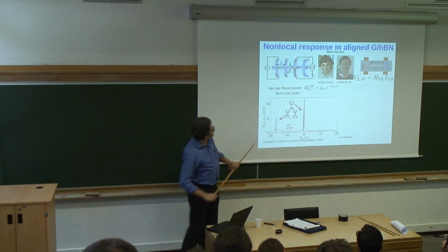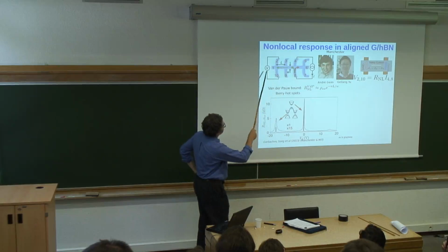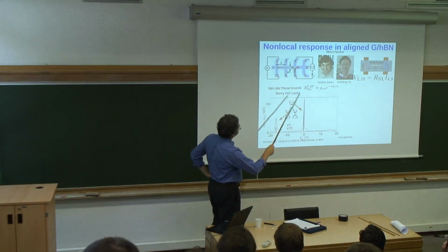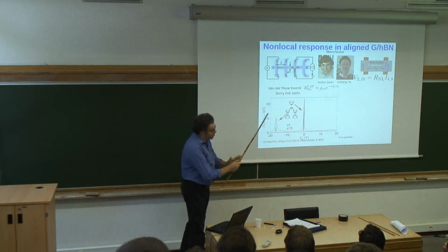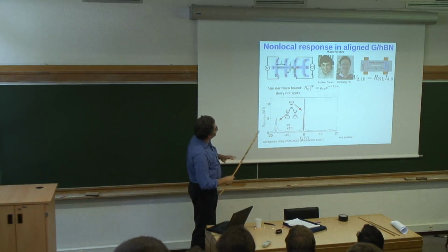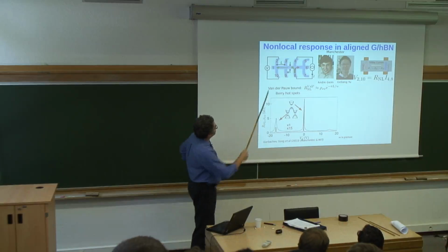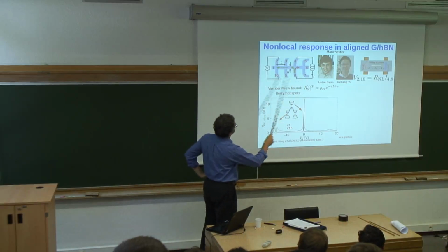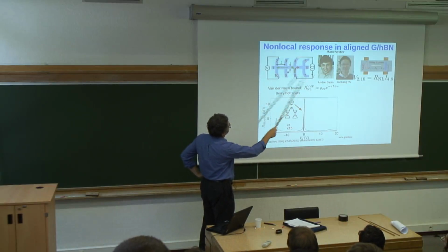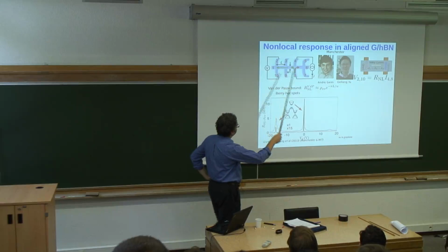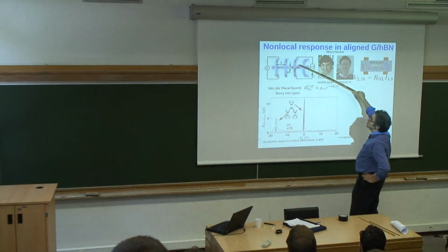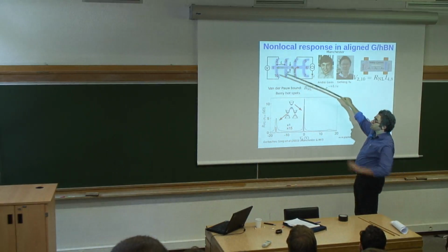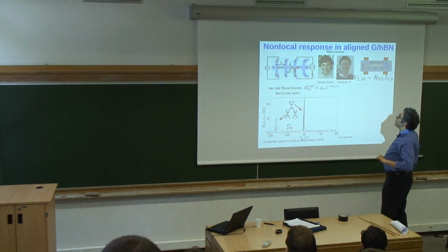Right. So the experiment is done in a graphene device which looks like this, and it's prepared the way we described. So we place graphene and boron nitride, axes aligned, find a place where it's clean, and then carve out a long bar. This length is about 10 micron with several side contacts, and then run current through one pair of contacts and measure voltage at a remote pair of contacts.